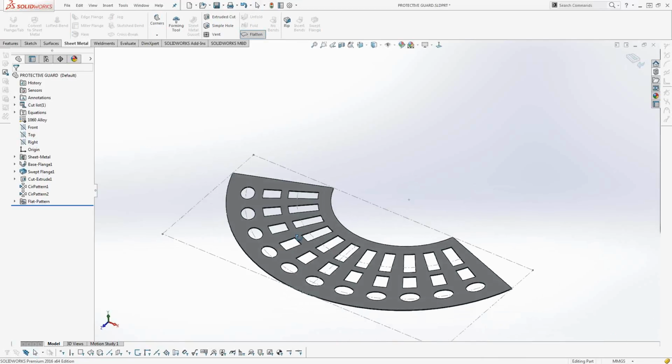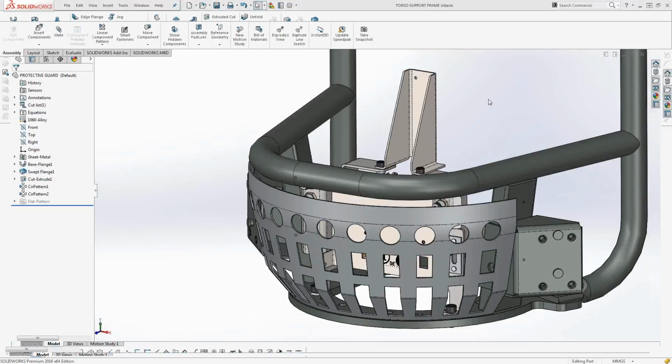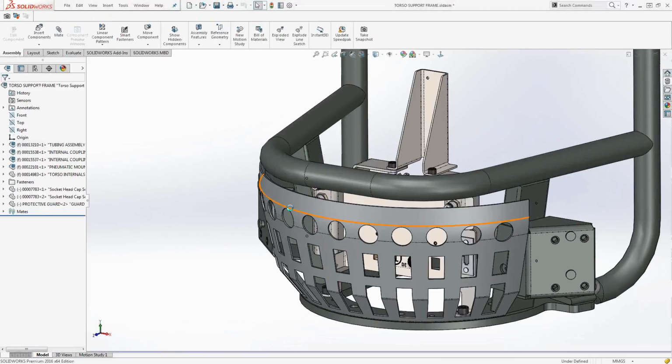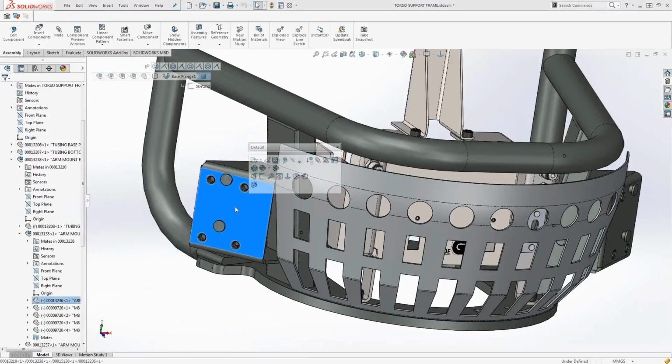Very, very cool. Speaking of limitations that have been lifted, this is a limitation that I've long wanted lifted within the tool. Let me switch back over to this part and let's take a look at this bracket that we have over here. I'm going to go ahead and choose to open this bracket, and I might highlight another feature within SolidWorks. Besides being able to select this face, this part, and open it, now from the pull down here, you can actually choose which subassembly you want to open. So I want to open up this subassembly that's 2 layers deep.